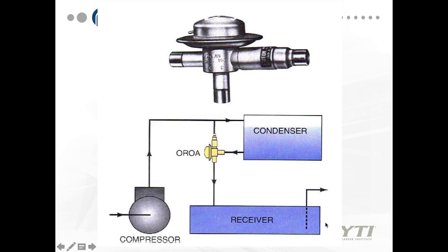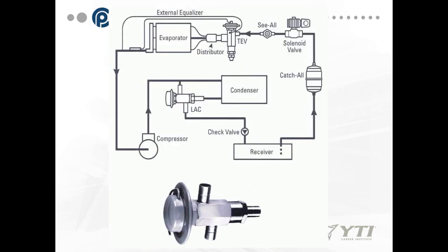Now this is important because we have to maintain an evaporator pressure. If my high side pressure drops because it's too cold outside, my evaporator temperature is going to drop, and we could freeze up evaporators or just make it less efficient. Okay, so by bypassing some hot gas, I can increase my pressures to maintain that evaporator temperature. Okay, and this is how basically everything we just talked about works into the system.